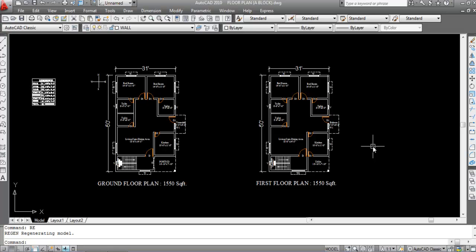Columns are the vertical members carrying loads from beams and upper columns. The loads may be axial or eccentric. Technically, a column is a structural member which is vertically and axially loaded and subjected to compressive forces, having an effective length 3 times greater than its least cross-sectional dimension. It is designed to resist axial and lateral forces and transfer them safely to the footings in the ground.